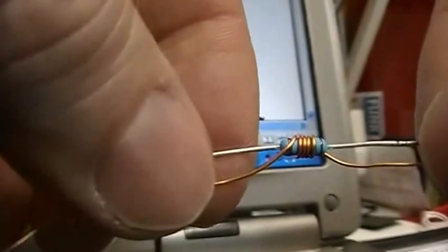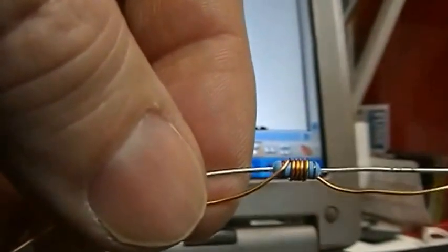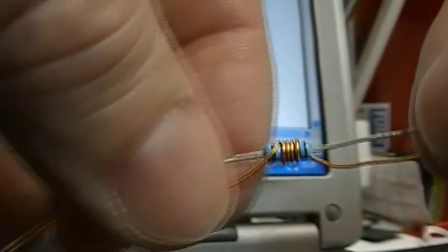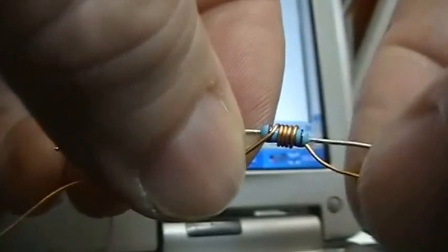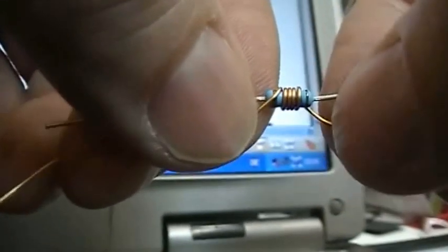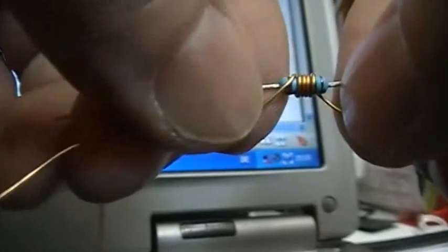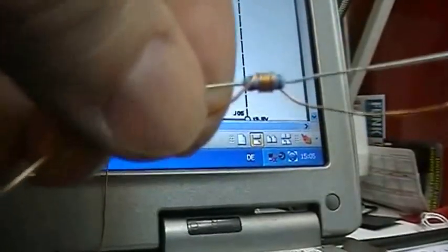Now we connect it to the resistor leads, and afterwards we will place it between base and collector on both final stage transistors, and we hope that we can stop the self oscillation with this little trick. We will see.